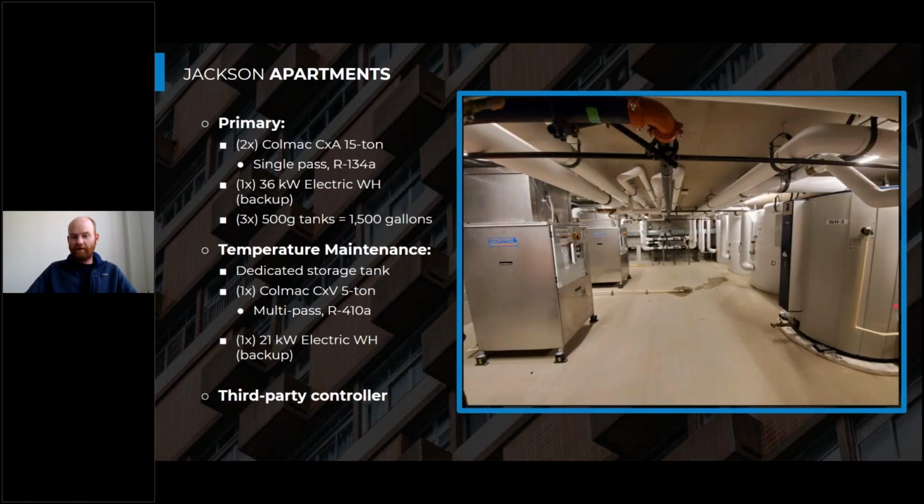The next few slides are just a few pictures of the heat pump water heating room. And yes, there's a lot of piping in here, and there's a handful of pieces of equipment, but I'll try to go through it to clear it all up. This system is designed with a dedicated temperature maintenance system, because it's a large multifamily building with a very large hot water distribution system.